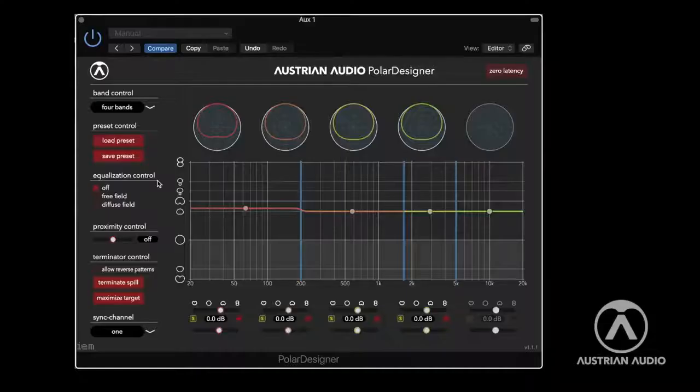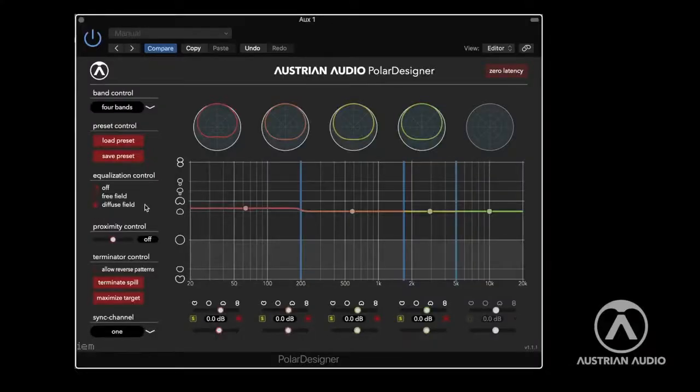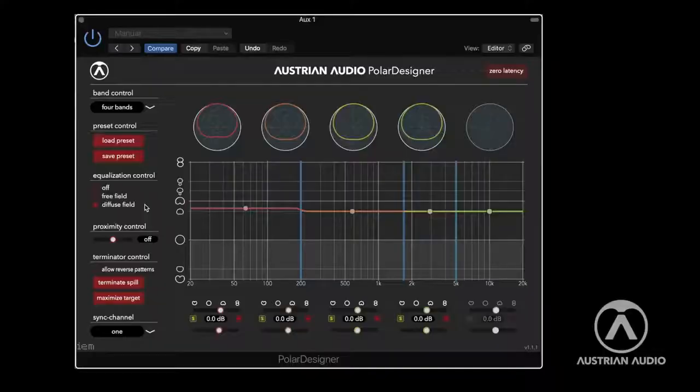And what this control does is equalize, that means basically cut the bass, so that this omnidirectional microphone sounds like a cardioid microphone. It cuts the low frequencies to get the same energy. And you will have the sound of the cardioid, because the cardioid is somehow the sound of the CK12, which is the most famous, let's put it that way. And you have the opposite too.